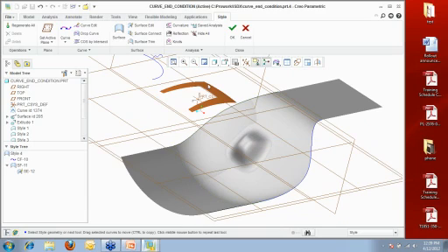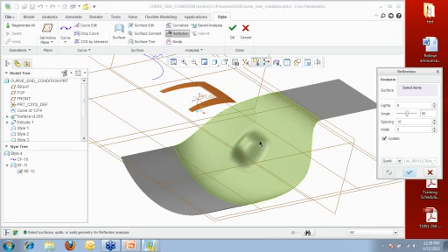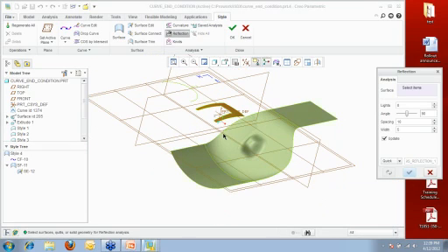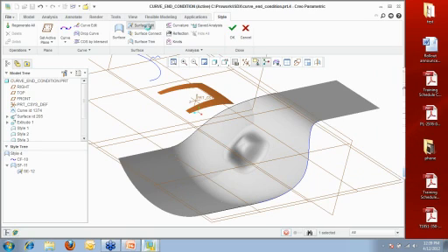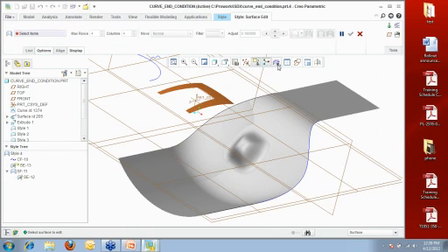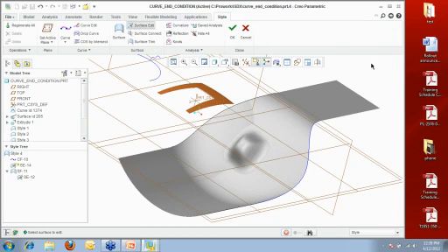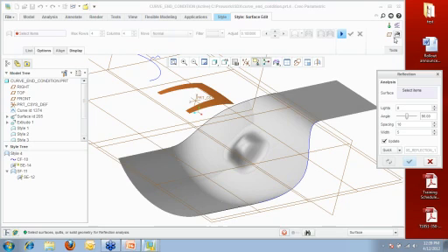Okay. Another thing that you have within the ISDX tool is the reflection, or essentially you have analysis functionality directly within the tool itself. So again, as you are editing, okay, you can come in and turn on the analysis tools. All right, let's go back to surface edit. Let's turn on the analysis tool. There we are.